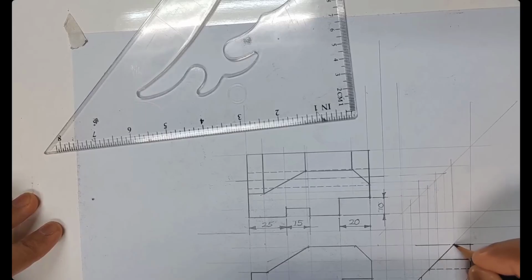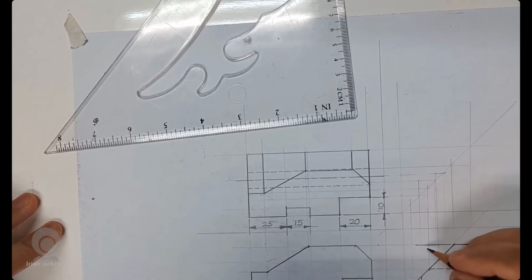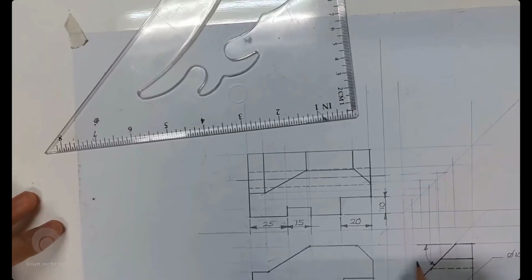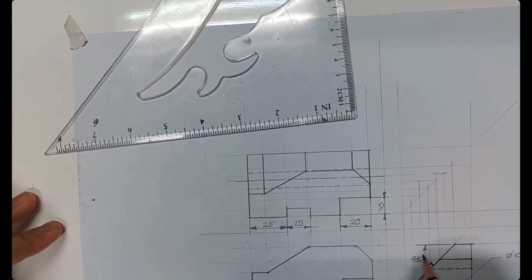I didn't have a compass, so you have to make the compass center point there, make an arc from this center point. Be careful, guys. You watching or not? This center point, your compass, your pointy, make an arc. So you make an arc like this, right? Using a compass, so your arrowhead will be like that. 3-1 arrowhead. As I mentioned, if you make a guideline of 3 millimeters, right? So this one will be 45 degree. Write it properly.